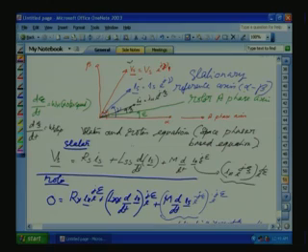So we assume the rotor current is also generated due to equivalent ABC phases, same like the stator. And if you see, the rotor A phase axis is here, but the rotor A phase axis will be moving away from the stator A phase axis because of the rotation. So the instantaneous angle is epsilon.